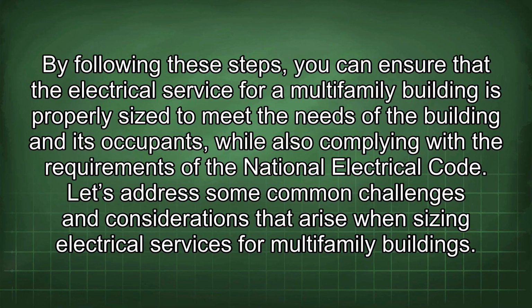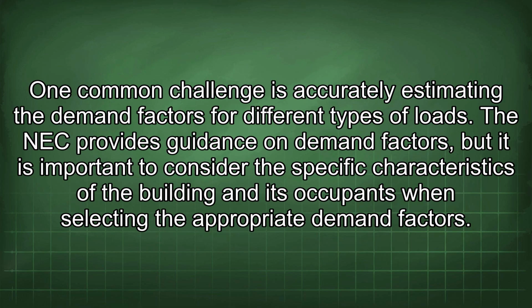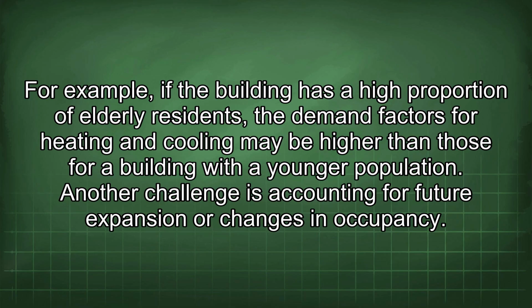Let's address some common challenges and considerations that arise when sizing electrical services for multifamily buildings. One common challenge is accurately estimating the demand factors for different types of loads. The NEC provides guidance on demand factors, but it is important to consider the specific characteristics of the building and its occupants when selecting the appropriate demand factors. For example, if the building has a high proportion of elderly residents, the demand factors for heating and cooling may be higher than those for a building with a younger population.